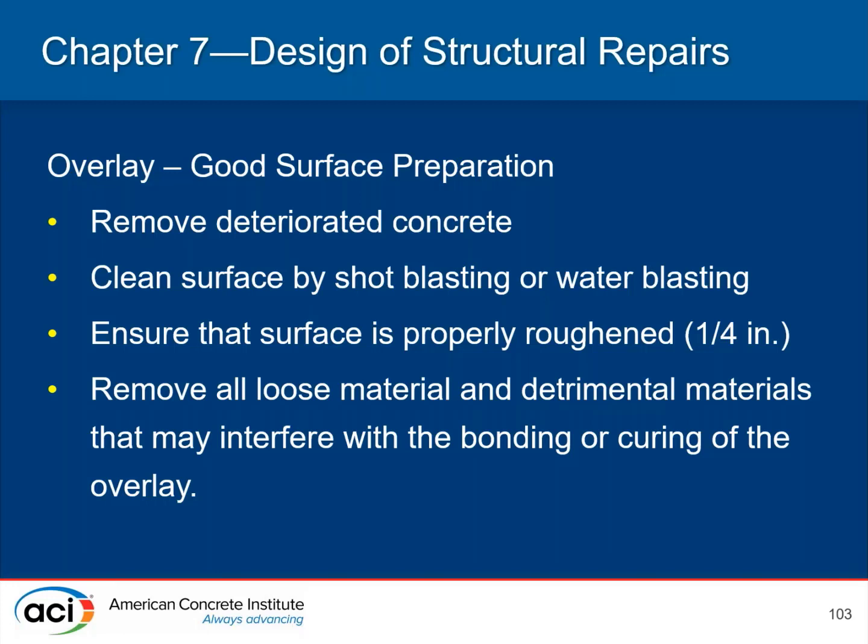For instance, moisture conditioning the surface, creating a good bond, however that's being accomplished, whether it be with a bonding agent or with a scrub coat of the repair material.